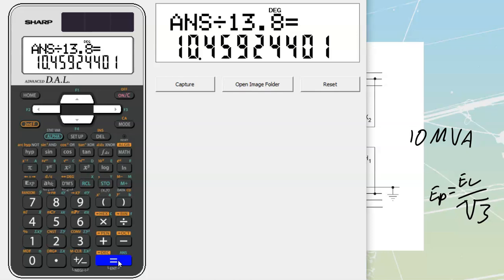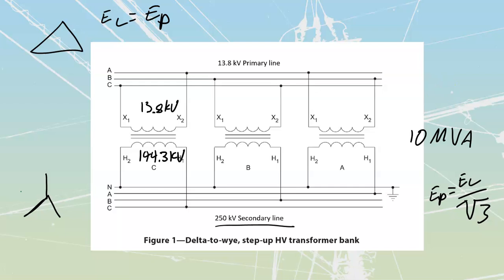In your book, they show you a different turns ratio. They're showing you the opposite, or the inverse, of what we would have over here. Don't worry so much about that one. It is a way you could write it, 0.0956 to 1, but it's much more common for your turns ratio to actually be your high side to your low side. So 10.45 or 10.46 to 1 that we will place in. TR is 10.46 to 1.